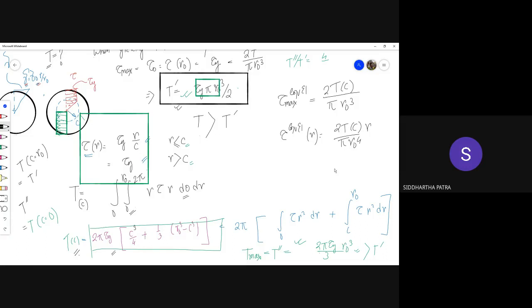So substitute the expression for Tc. And this expression remains the same, because the unloading is elastic everywhere. So this expression remains the same for both the parts, the part that is above C and that is within C. For both the parts, this is the expression for the equivalent elastic stress of this torque right here. And that actually is unloaded.